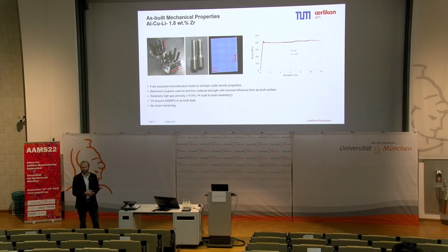I think in a lot of studies, we find a good process parameter set and then we go ahead and apply it. But that's not always going to lead to repeatable results in the long term, especially if you think about moving the parts around on the base plate. We know there's a large spatial effect in the different locations on the base plate. We can get different density values.